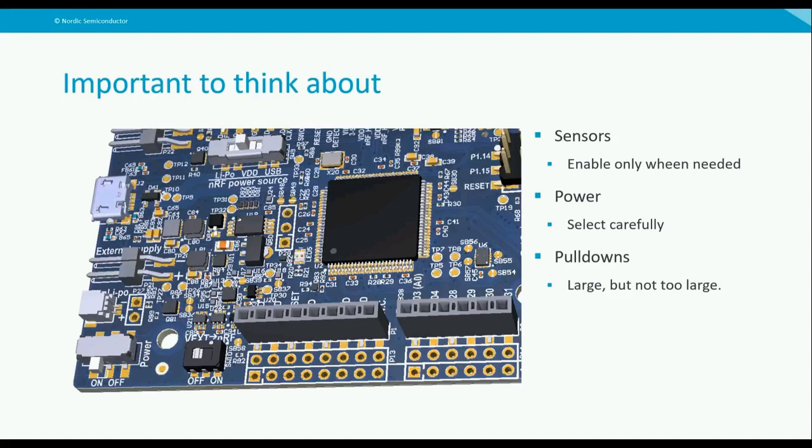As I mentioned previously, it might not even be that you need an accelerometer or IMU that gives you data all the time, from all the directions. Maybe you just want to know when your product has flipped upside down. Then you can choose an accelerometer that gives you a single signal telling you exactly this, and not all the other axes that your product doesn't need.